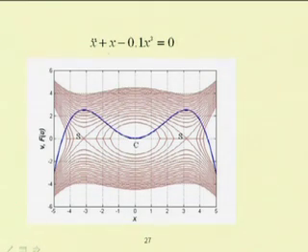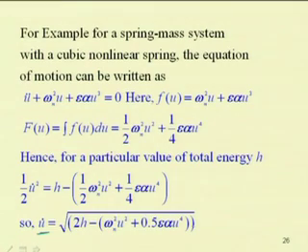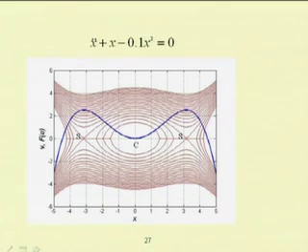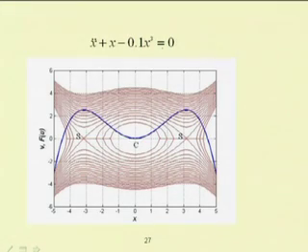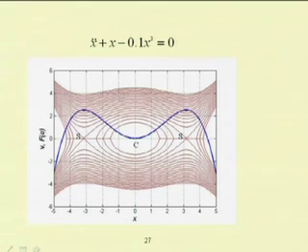So, either you can find this equation, this potential well, by using this equation, or you can find that by solving this differential equation by different methods, numerical methods. For example, you can use the Runge-Kutta method to find the response of this system. This second order differential equation can be written in the form of 2 first order differential equations and can be solved to find x dot and x. And one can plot that response.